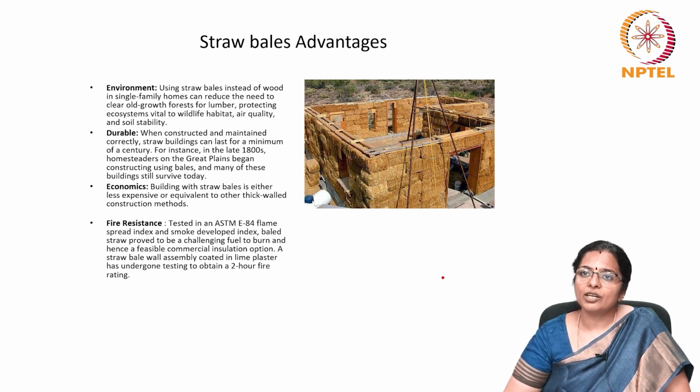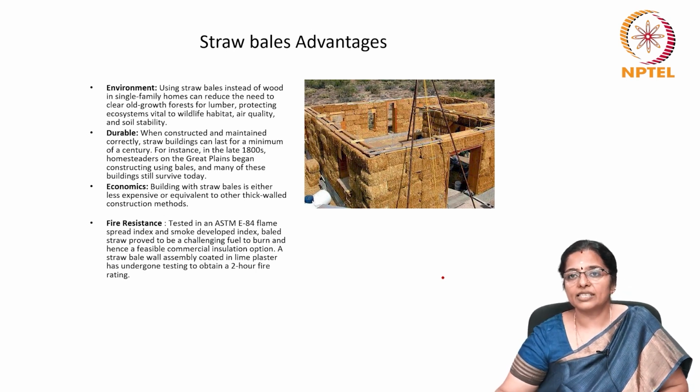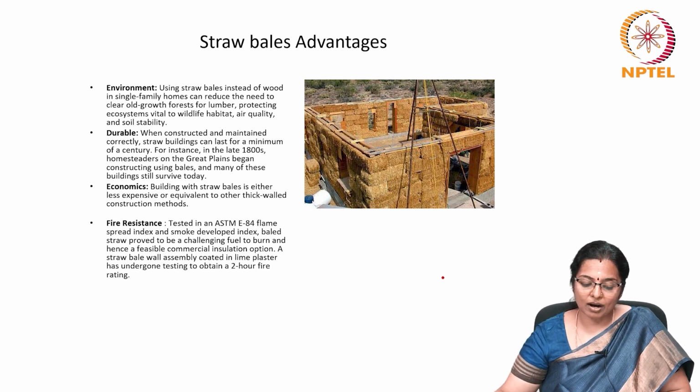They are equivalent to other thick-walled construction methods. They are fire resistant too. A straw bale wall assembly coated in lime plaster has undergone testing to obtain a 2-hour fire rating.